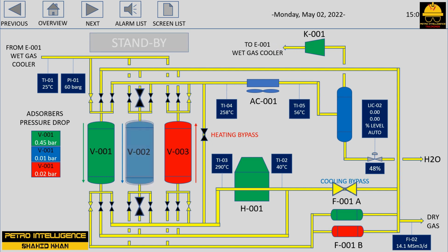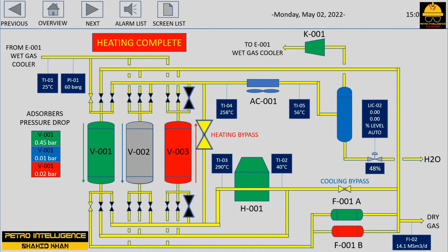Regeneration operations take various forms, depending upon the system. If the period of time required to saturate the bed is relatively short as compared with the time required for regeneration, there will usually be an alternate bed to which the feed is switched. At other times, the bed may just be bypassed or the unit shut down while regeneration takes place.